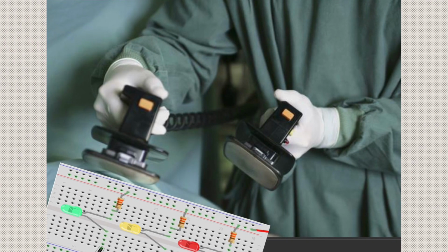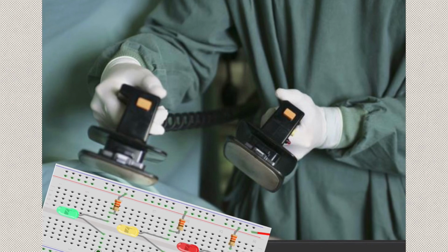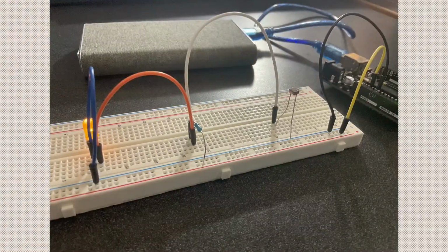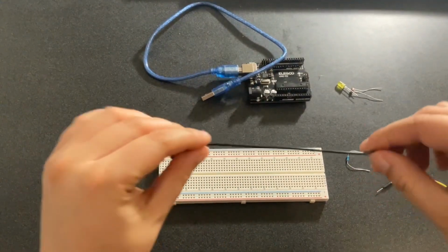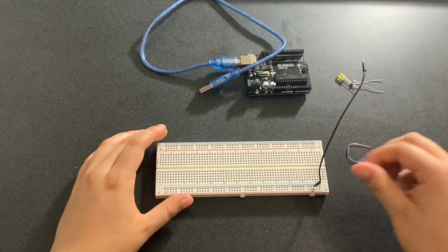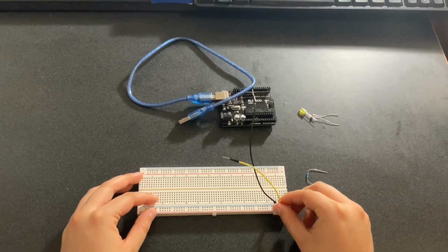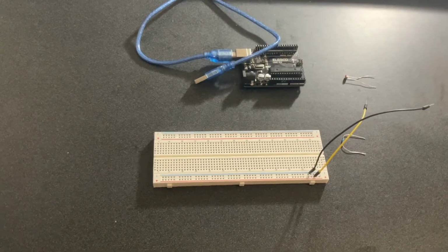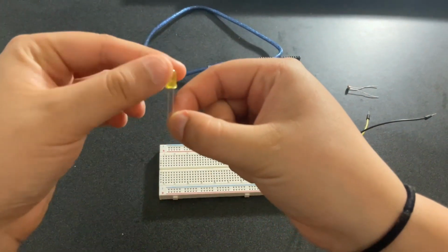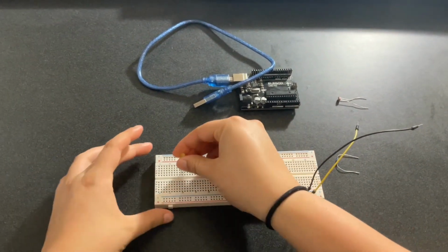Now, let's bring our circuit to life on a breadboard. Follow along as I demonstrate the assembly process step by step. We want to begin by identifying our negative cable and connecting it to the ground port. Then we plug in our positive cable into the positive port. Next, we want to find our LED light bulb. I chose yellow, and identify the positive and negative sides. This can be done by seeing the shortest side, as that is the negative side, and then connect that to the breadboard.